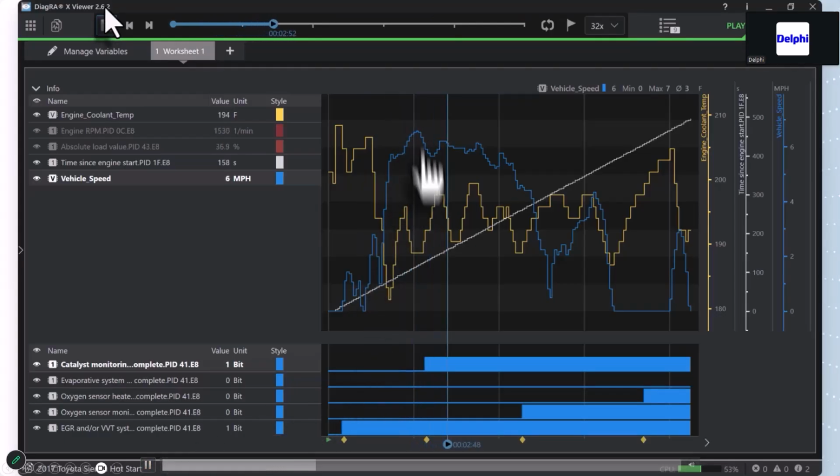If you notice right here, I'm on the freeway. I got right back on the freeway. When I did, the VVT went right away. The cat ran first at cruise. The O2 ran second on this slight deceleration. And notice what happened over here at idle. The O2 heater ran. So that's why I don't want you to get locked into the patterns.